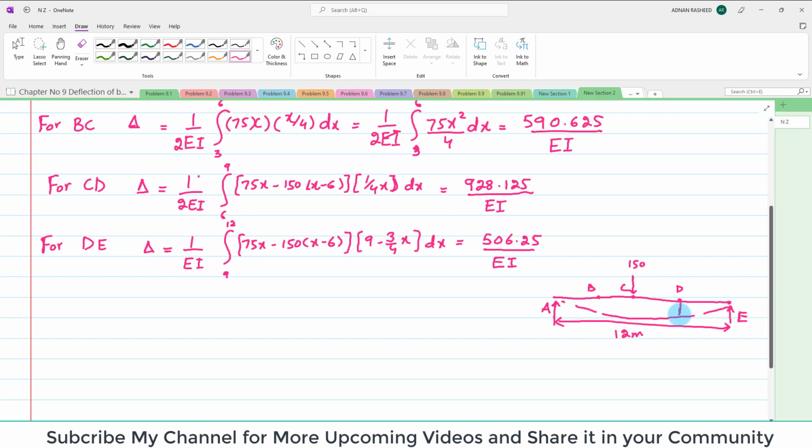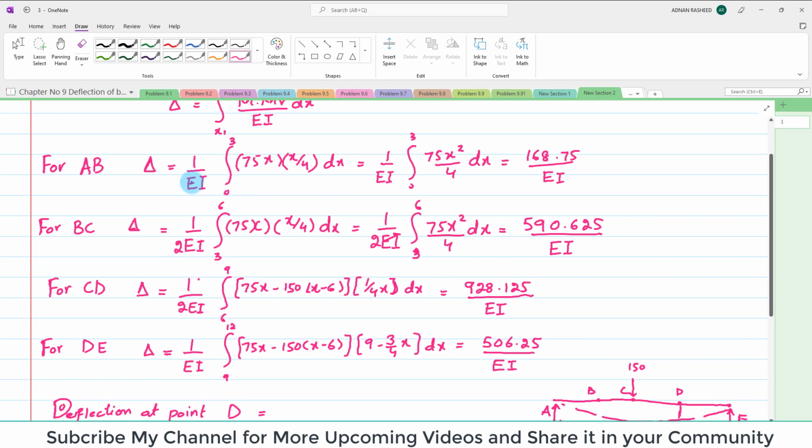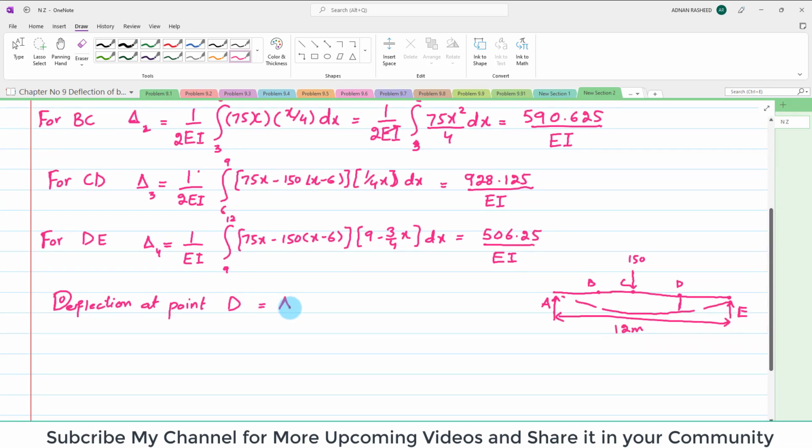In order to find this deflection, let me call them delta 1, delta 2, delta 3 and delta 4. So you can see delta 1 plus delta 2 plus delta 3 plus delta 4. Why? Because the deflection from A to B, from B to C, from C to D and from D to E will give you the deflection at the end.